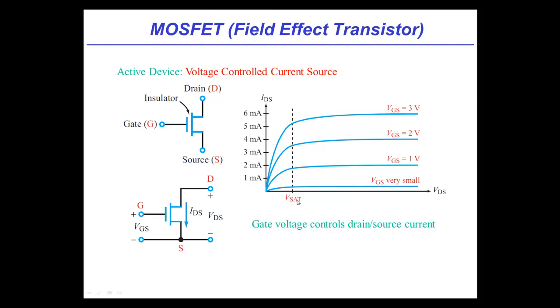That's right. Now, there's a transition region, as I mentioned earlier, at low VDS, where that nice ideality goes away, and in fact the current does depend on VDS as well. So in this region, the current depends on both VGS and VDS. But if I look at this and pretend these lines go through zero, I could almost convince myself that for low VDS, this looks like a resistor between drain and source, and VGS just changes the value of the resistor. That's right.